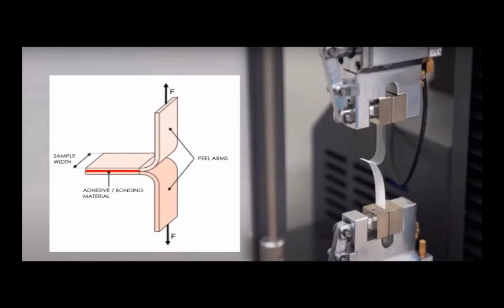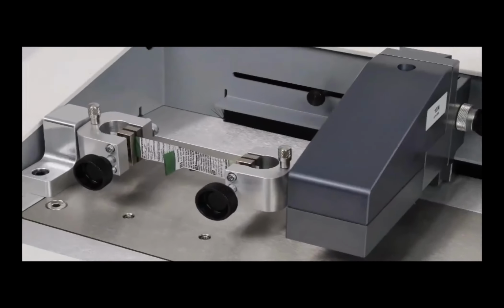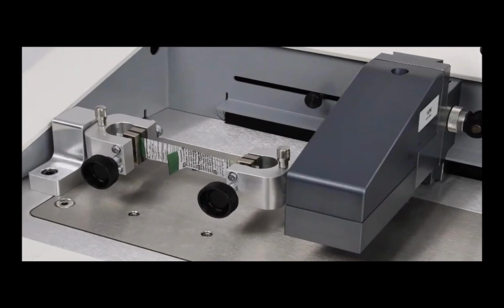So typical materials that perform T-peel testing are those that use leather, plastic, rubber, and soft metals such as foils to bond, weld, or otherwise seal two or more pieces together. So again, the T-peel test procedure is commonly used when both materials are similar or both are flexible. For example, to measure the peel strength of flexible laminates. It requires both bonded substrates to be flexible enough to bend the 90 degrees without breaking.